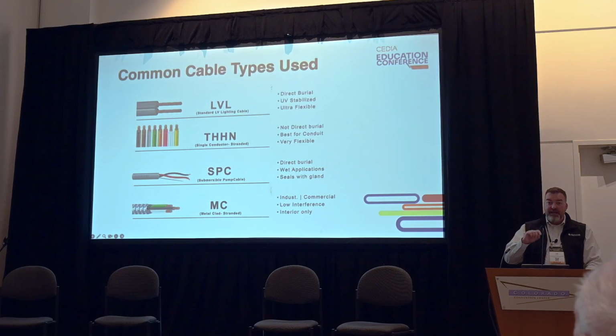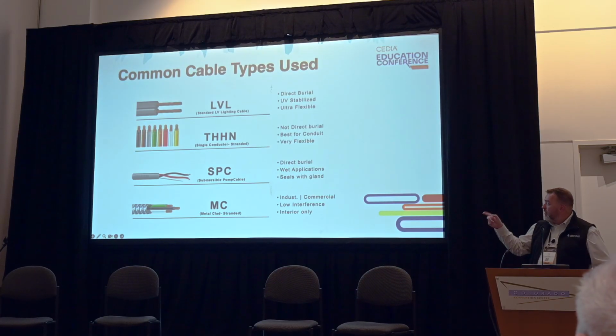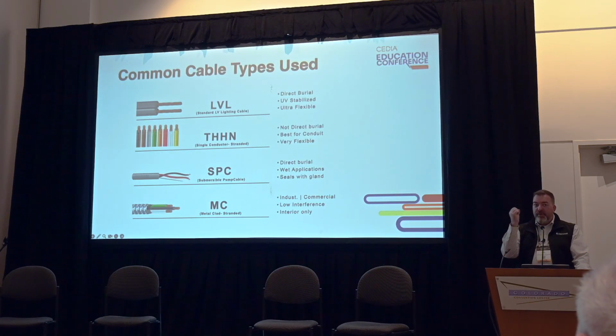You're going to see this type of cable coming out of underwater fixtures or some hardscape fixtures where they almost have a pool gland where they're sealed up inside. You're going to have that round jacket. Inside that, what we recommend is on the ends of those, seal them up with an adhesive-lined heat shrink, so water can't go up because you're going to get a vacuum effect.